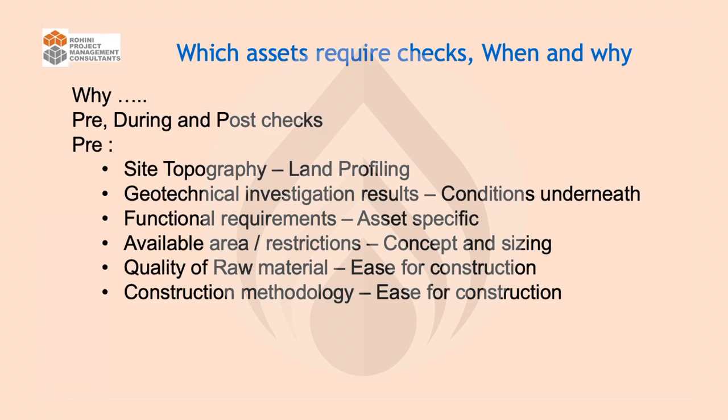You need to understand the site topography, to understand the land profile. You also have to have geotechnical investigation results to understand the conditions underneath. Obviously, that is very much required because you are going to have some structure which is going to start from the bottom, right? And where to found it. So the conditions underneath is very vital to be known.